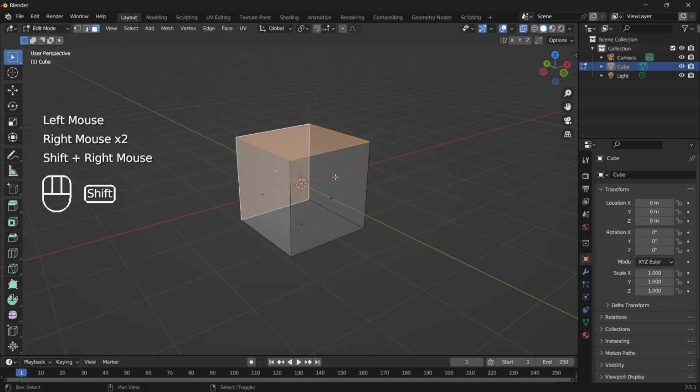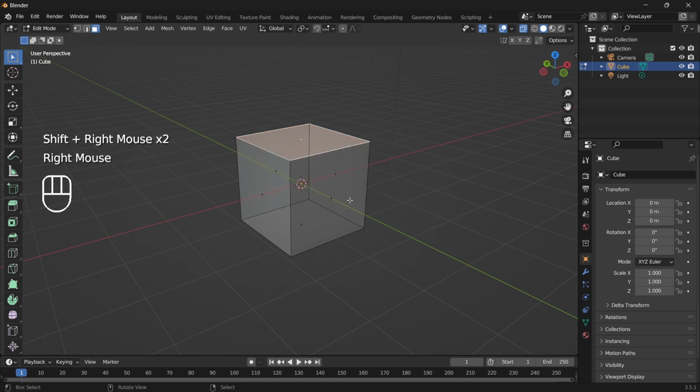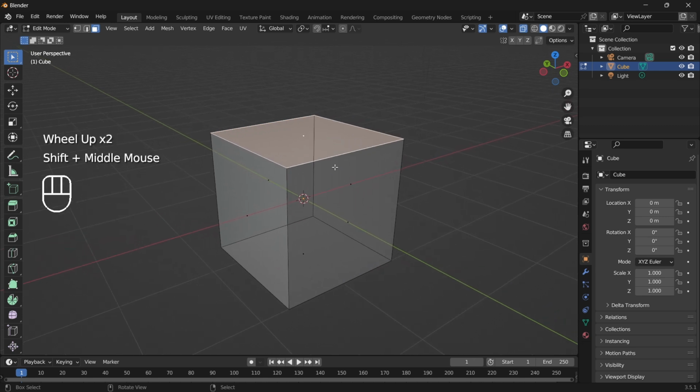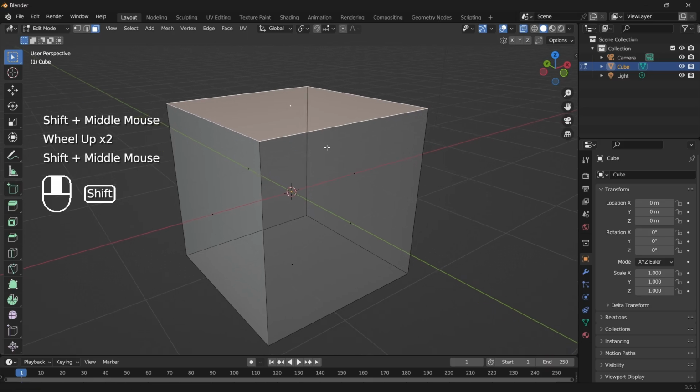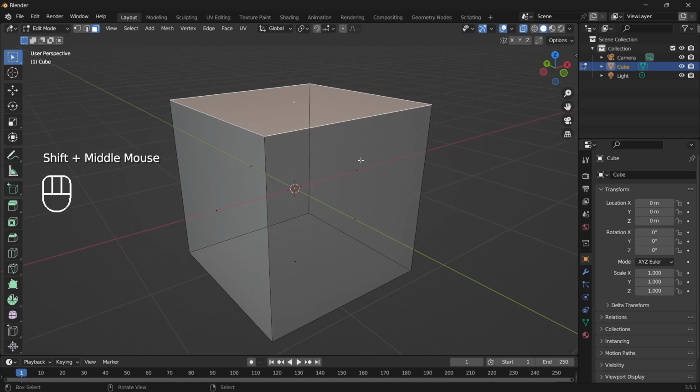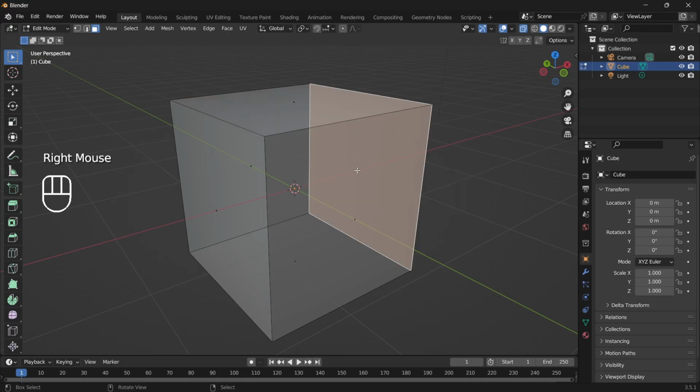You can select faces. Now, when you're selecting faces, you'll want to keep in mind that in order to select a face, you're going to come close to this point, which is located in the kind of calculated center of the face. When you click near this point, it determines which face you're trying to select.